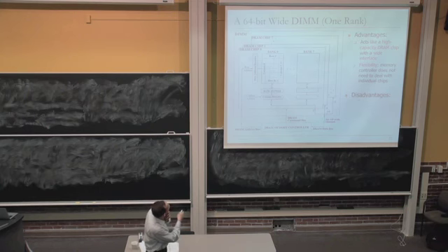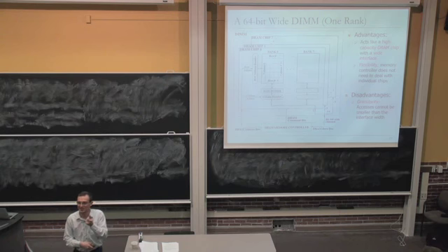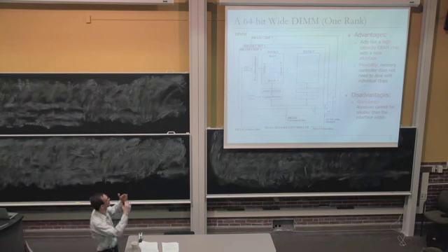The disadvantage of a wide interface is granularity, right? What if you actually want to read 8 bits? Now you cannot. You have to read all of the 64 bits, which means that you waste some energy, right?